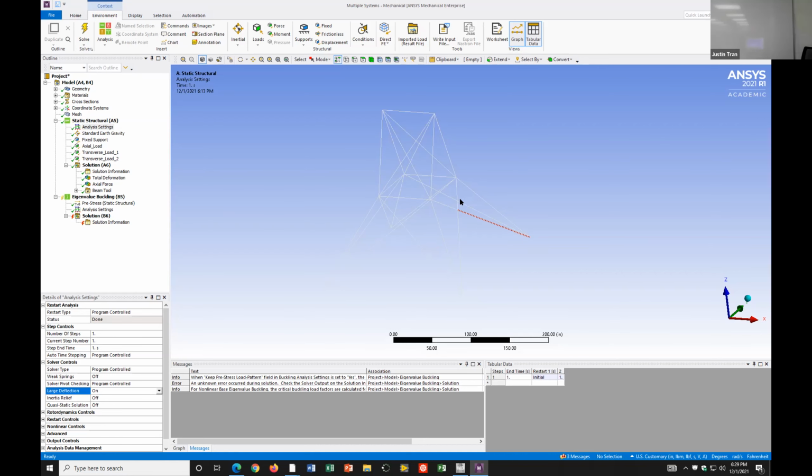So what this means, these are all modes. If you take this number and you multiply by all your modes, that's going to cause buckling. So since your multiplier is less than 1, that means the structure is buckled even before these modes, 77%. And if you try 76% of the mode, then it's going to follow like this.